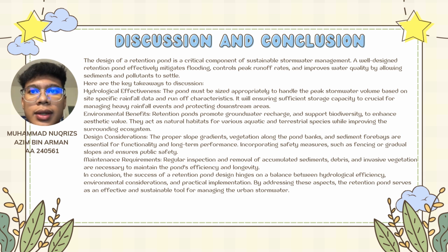Lastly, maintenance requirements. Regular inspection and removal of accumulated sediments, debris and invasive vegetation are necessary to maintain the pond's efficiency and longevity. In conclusion, the success of a retention pond design hinges on a balance between hydrological efficiency, environmental considerations, and practical implementation.